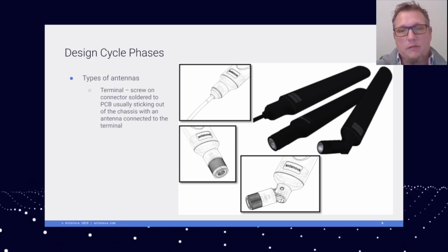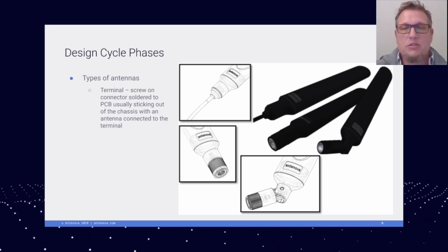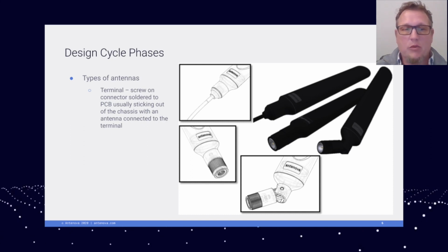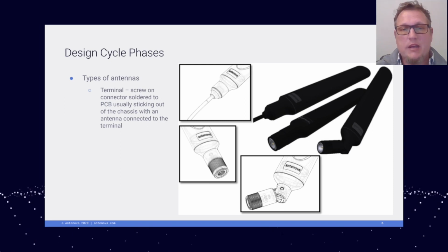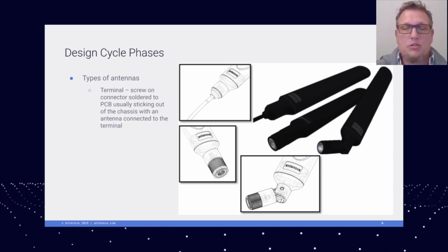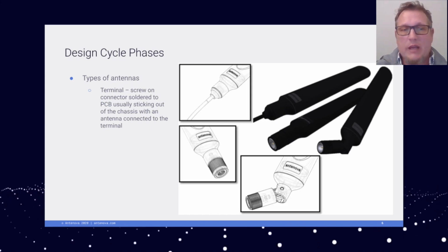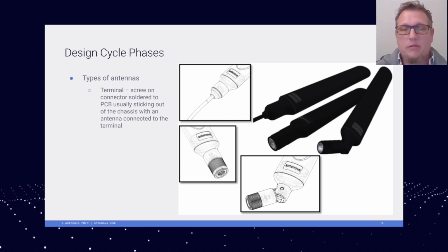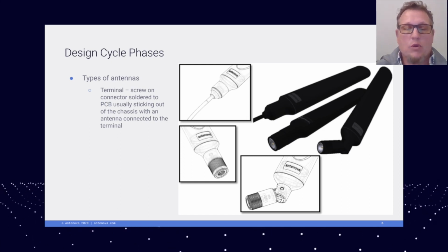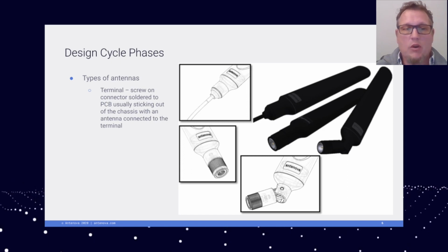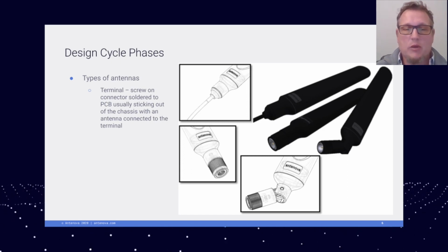So the efficiency on these antennas tends to be a lot better because you can get them away from your device, the ground plane, or any other metal parts of your device that tend to cause issues with the antenna performance. They are also not ground plane reliant because they have a balanced antenna structure inside of them, and therefore you can mount them pretty much anywhere on your device without having them be detuned by a smaller ground plane.